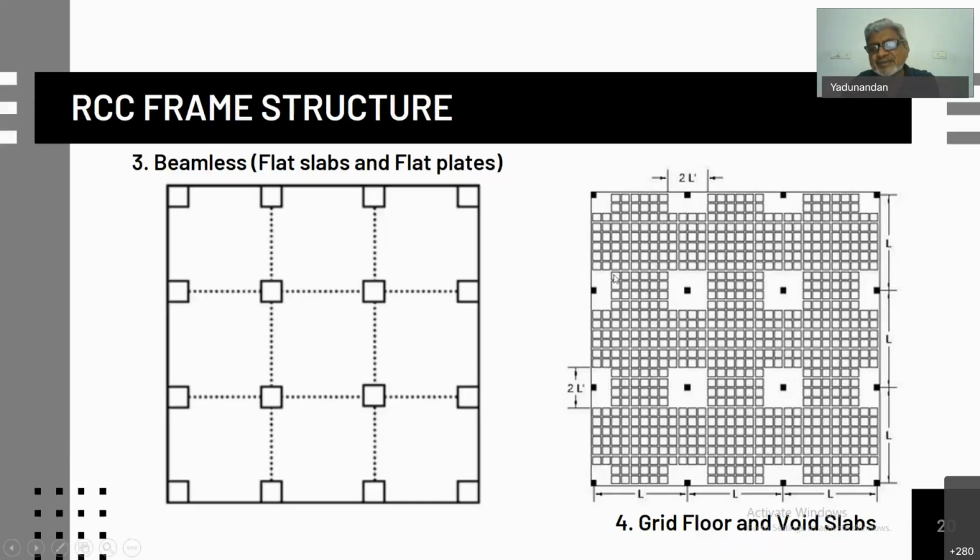It still acts like a slab system, but it is a slab with a cross section with ribs very closely in between. It is sort of a grid floor. The effect of the grid floor is obtained by providing voids and by formers which are kept, and then the ribs are automatically provided there, and they also act like the grid floor only.